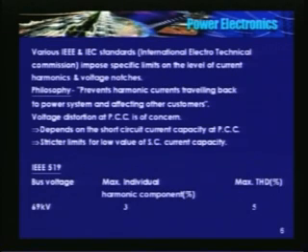Now various agencies enforce certain norms. The philosophy is if you are generating harmonics, you do not transmit them back to the source and affect the other loads. You better take care of the harmonics that you have produced. In other words, voltage at the point of common coupling should not get distorted.